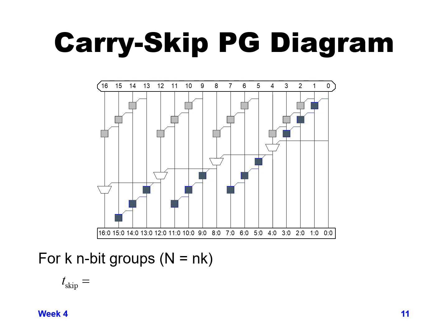And at this point, you can see that the carry coming out of bit 4 is being calculated at the same time and in parallel with the carry that's going to come out at bit 8, the carry coming out at bit 12, and the carry coming out at bit 16, or I should say the generate bits. So that will go through 3 boxes, and it will hit the mux looking box there that's in white and go through that delay.